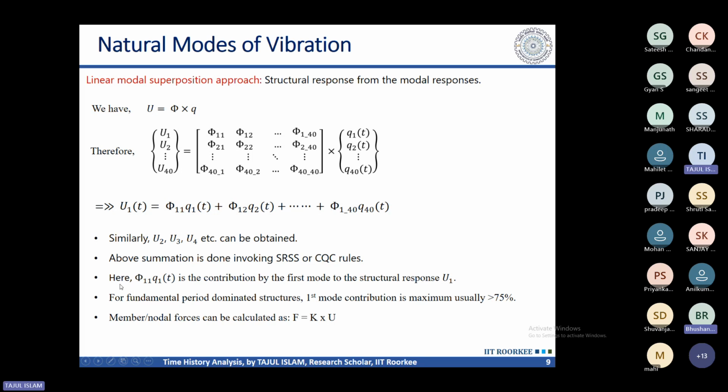Yes, hello, Raju, please. One question, you can answer it later. We have the stiffness K and mass M, from which we get the eigen solution. So that 12 EI by H cube, the formulation that we use, is the software also using the same way, or is it calculating the stiffness in some other way? That is part of the discussion already, so you'll understand. Yeah, thanks.